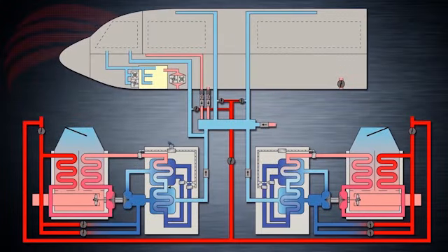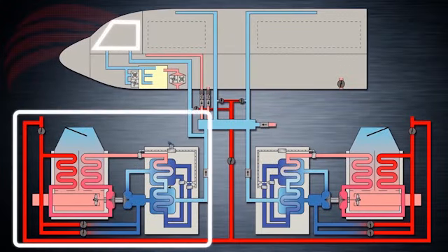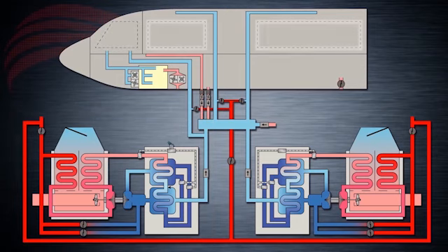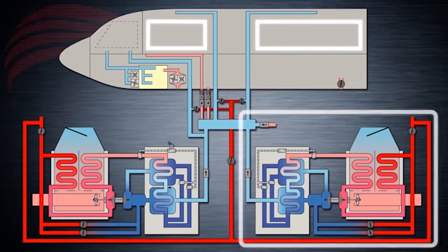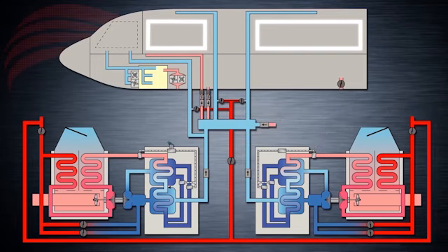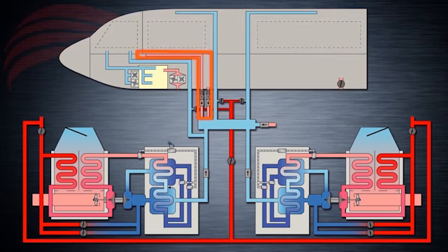Moving on, air in the flight deck is 100% fresh air from the left air conditioning pack. Air in the passenger forward and aft cabin is a mixture of fresh air from the right air conditioning pack, the mixed manifold, and a certain amount of air that is recirculated within the cabin. We'll now discuss a little bit about the recirculation process and its function.